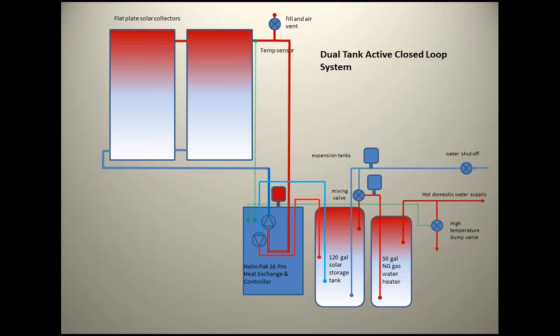The water from the domestic water is pumped one way, this way, and the water from the solar house, from the water solution, is pumped the other way. And so they're pumped past each other through two concentric tubes. So it's called two heat exchangers. There's a tube within a tube, and propylene glycol passes one way, and domestic hot water passes the other way, and that heat exchange happens in this commercially available appliance.